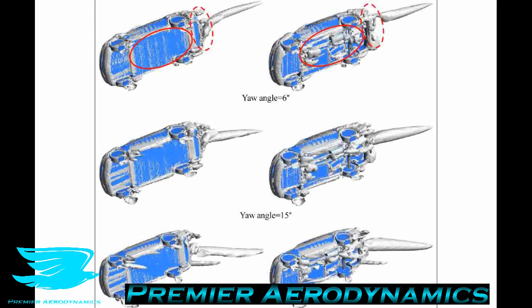Okay, so I assume that you've paused it. If you have low pressure at the back of the car, more low pressure, that's going to increase the pressure drag of the car, increase the drag in total. Also, these vortices at the back are probably going to change the lift characteristics as well, and where the downforce and lift are being produced along the car.